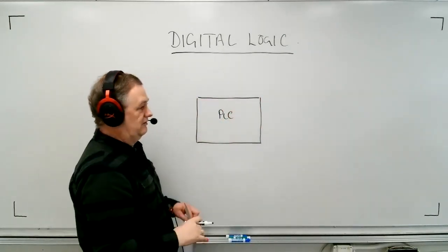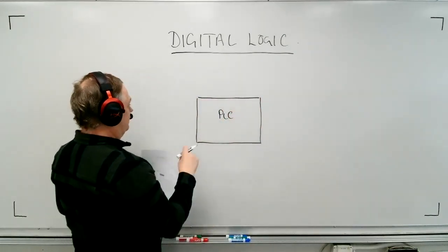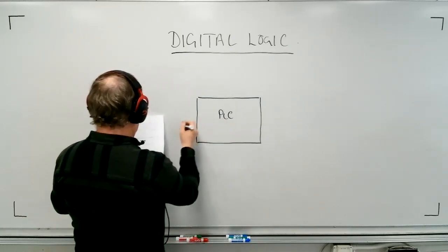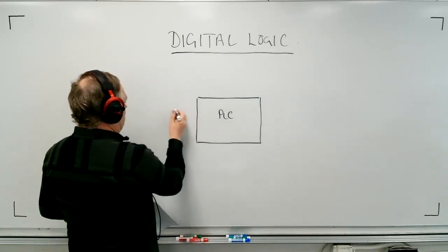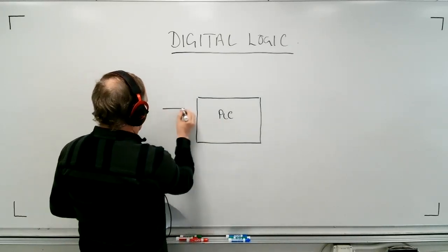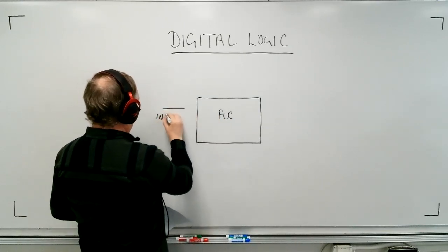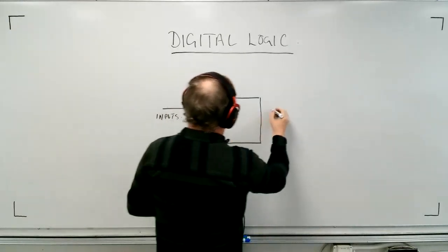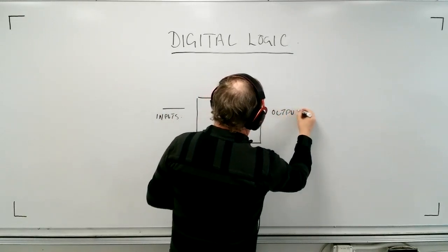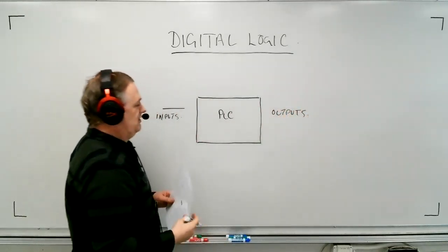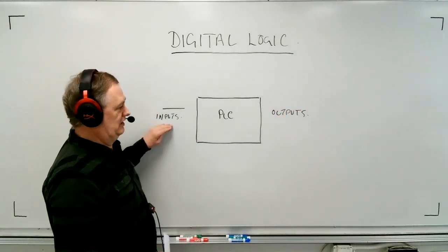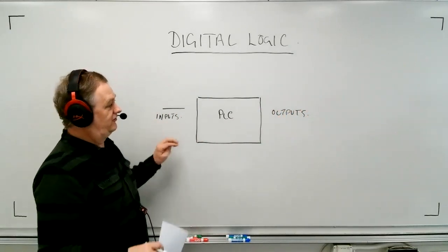Okay, so we have typically all sorts of automated controls, but let me just give you this idea. To a PLC, you would actually have inputs and outputs. And essentially, these are normally fairly low voltage and current circuits, 120 volts or less.